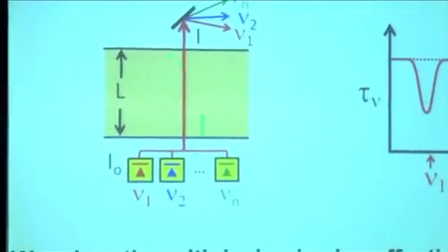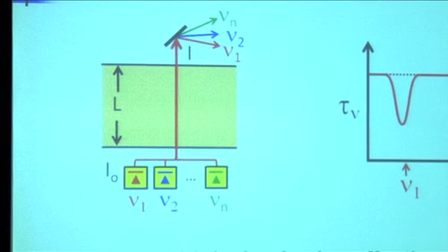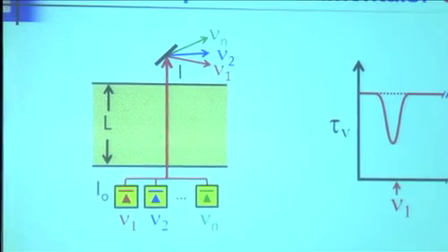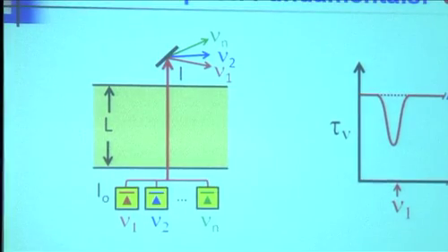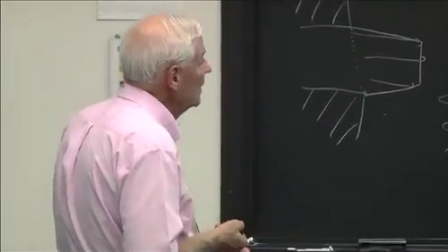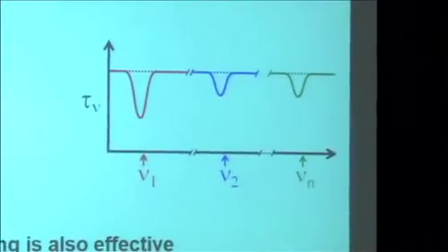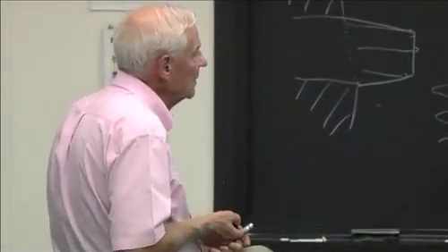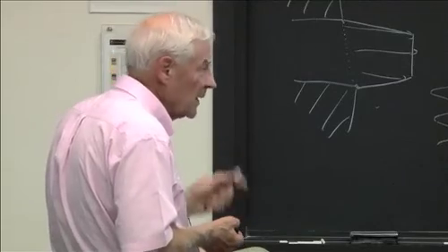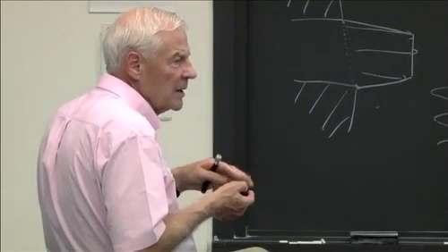If you have non-uniform conditions, the biggest question you always get is, well, how do you know it's uniform, or what happens if it's not uniform? That's the biggest problem. It is a path integral measurement. But if you know the distribution, that is, maybe you know it's parabolic or something, you can use that to advantage. Or you can make measurements at different quantum states of the same species, which means each one will have a different temperature sensitivity, and you can unravel to some extent the spatial non-uniformities. But that's a problem. So usually we design around it and we try to pick wavelengths that are insensitive to this.